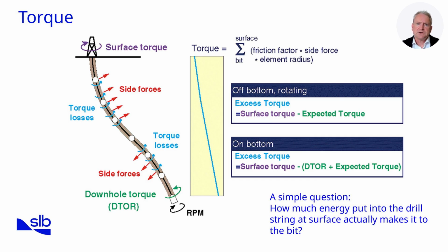The driller should take regular measurements prior to making a connection to note the pickup, slack off, and off bottom rotating torque. This enables the trends to be plotted compared to what is expected. The measurements can be plotted on what is called a broomstick plot, which is a modelled pickup slack-off chart, where the actual measurements give early warning if the trend changes compared to the plan.